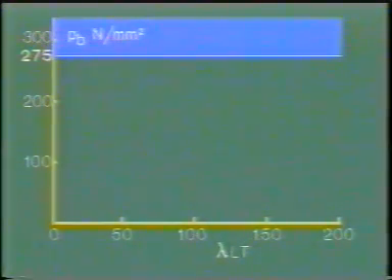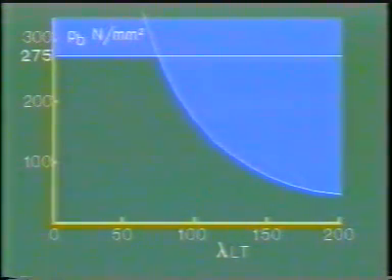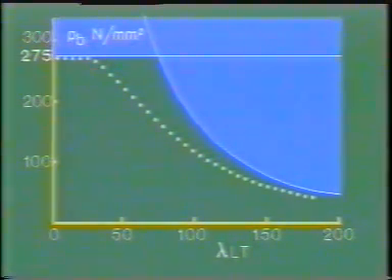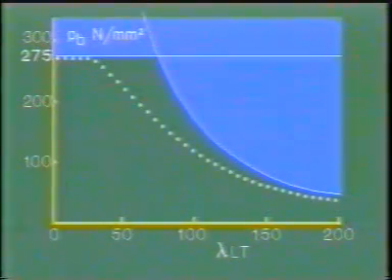In terms of extreme fiber stress, this behavior plots as a line which has a very low value when the slenderness is high, but has a very high value when the slenderness is low. This line, too, is an upper bound to the actual bending strength. For low slenderness material, strength is the limiting condition. But for intermediate values of lateral torsional slenderness, where plasticity and instability interact, the values of design strength represent a realistic, safe solution, with the reduced material bending strength being lower than the yield strength and also below the instability curve.